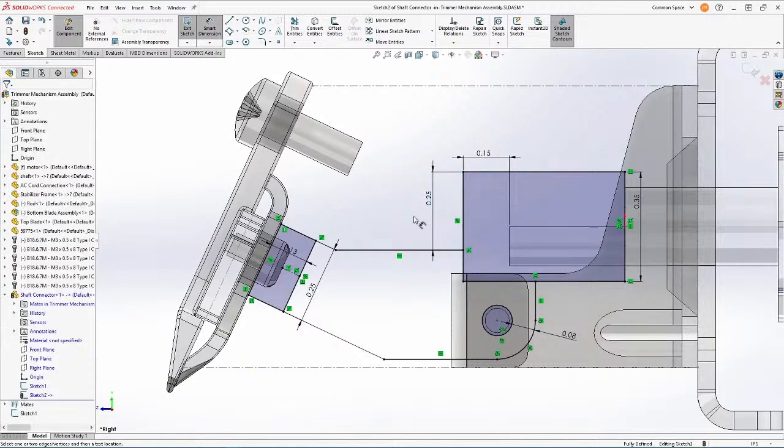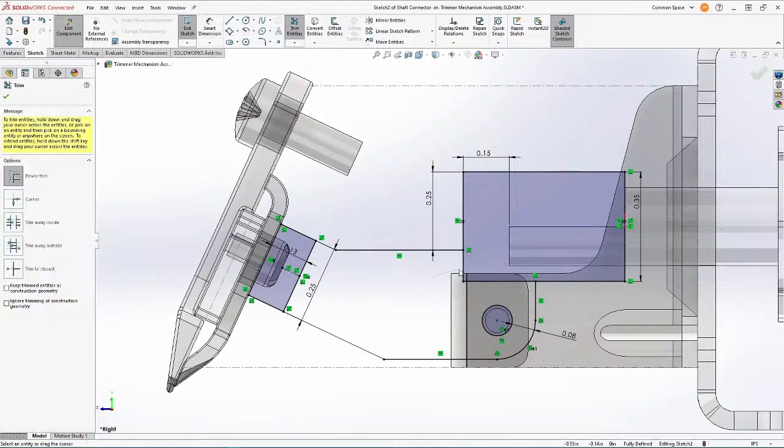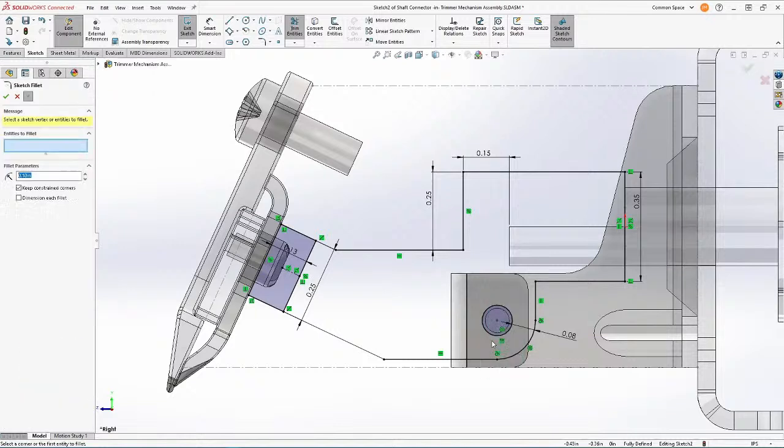And then it's time for my big pro tip, the S key. For all of you SOLIDWORKS users, you're very familiar with this one, but if you press the S key, it pulls up a shortcut menu, and it lets me jump into things like the trim command in this instance. And again, this just keeps my mouse focused on where I should be, right in the graphics area. So I'm going to round off some corners relatively easily just by selecting a vertex. Of course, with those changes, I can just go ahead and click the green check.